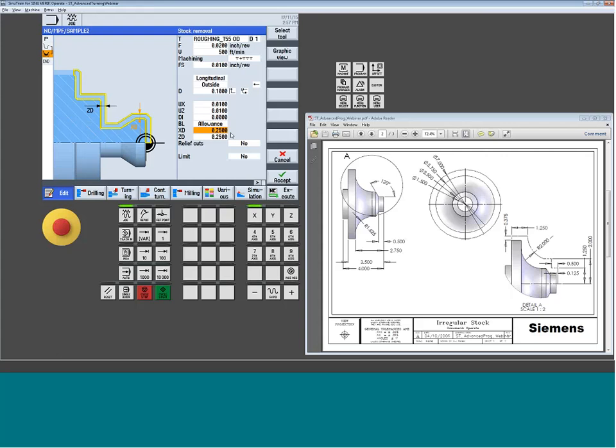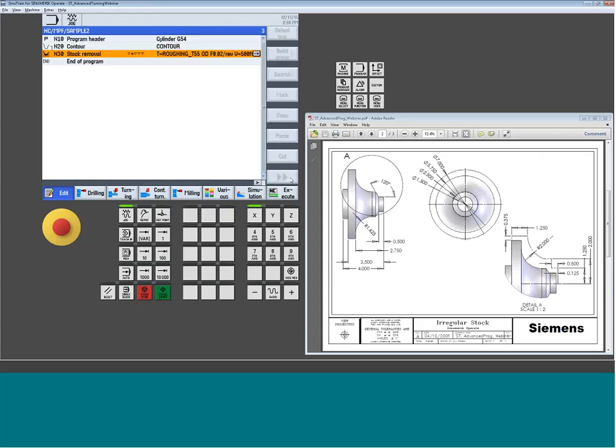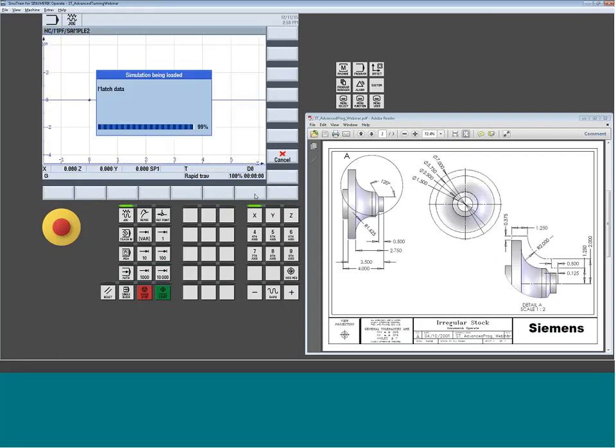So here, I'm just going to say, and it can be a different value, it doesn't have to be the same, but it will be the same for all X surfaces or all Z surfaces. I'm saying I've got a 1/4 inch of material on each of these two surfaces. Now, I don't have any relief cuts because I'm not dropping into any pockets, so I can leave them off. We accept it, and now you're going to start to see this optimized cutter path.